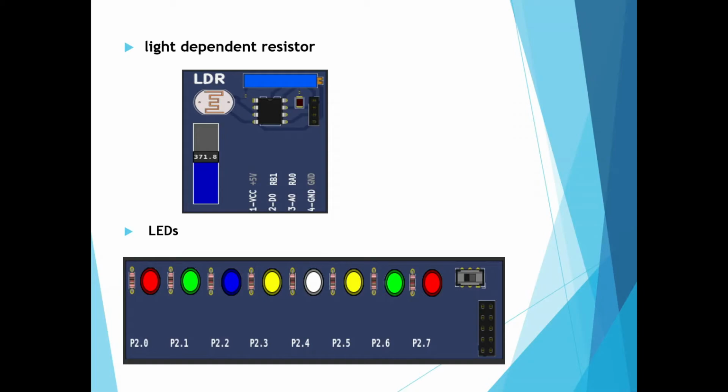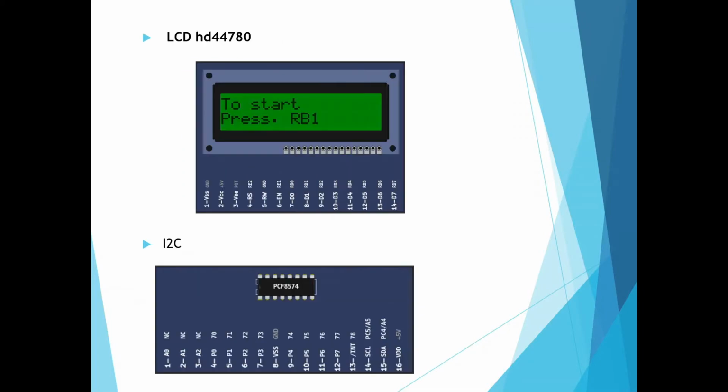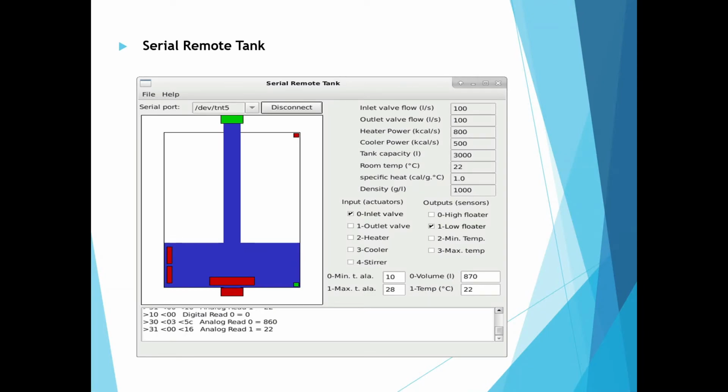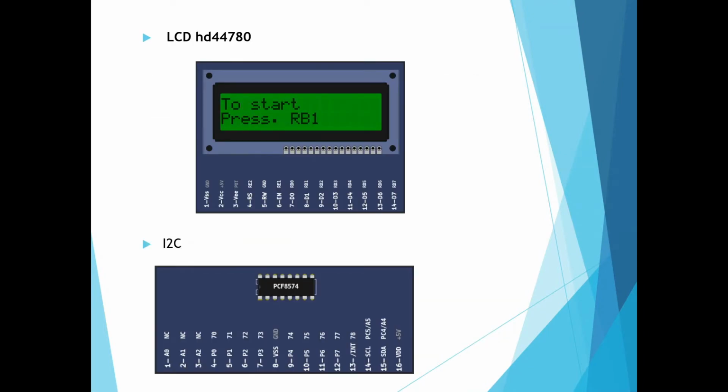Next, our component is liquid crystal displays. The LiquidCrystal library allows you to control LCD displays that are compatible with the Hitachi HD44780 driver. There are many of them out there and we can usually tell them by the 16-pin interface. The LCDs have a parallel interface, meaning that the controller has to manipulate several interface pins at once to control the display. The interface consists of the following pins: a register select pin that controls where in the LCD's memory you are writing the data to.